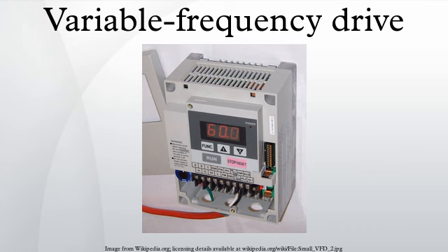For example, at 63% speed a motor load consumes only 25% of its full speed power. This is in accordance with affinity laws that define the relationship between various centrifugal load variables. In the United States, an estimated 60 to 65% of electrical energy is used to supply motors, 75% of which are variable torque fan, pump and compressor loads.